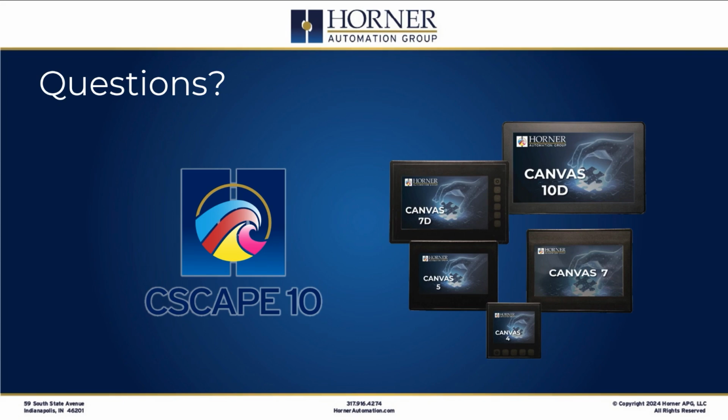There will probably be a prompt for you to examine a map of the fonts that you used with Cscape 9 and the fonts that are going to be selected in Cscape 10. So that will probably be displayed, a dialog box that shows you how we're going to map the fonts, because the fonts are much more extensive and much more flexible with Canvas than they were in an XL7, for instance. And then after that conversion, it's going to be mainly touch-up, as Casey has mentioned in his reply.